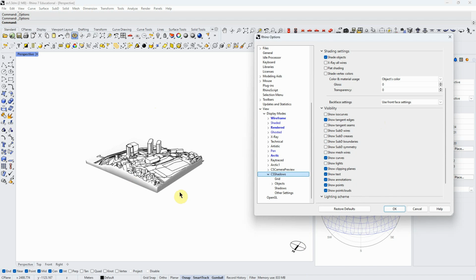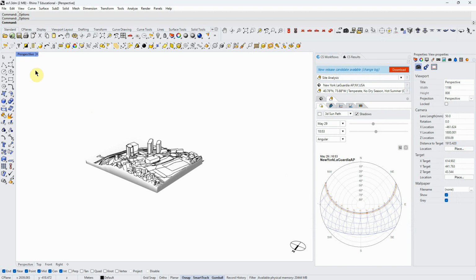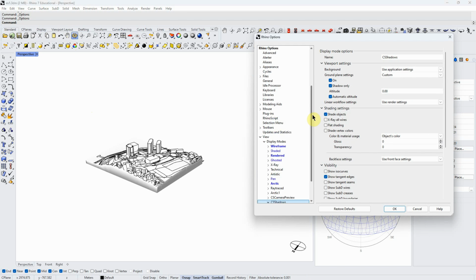It's not working because... by the way, let's go back to that. In Rhino, in the standard tools, there's the settings wheel. You click on that. If you haven't used it before, you've got document-specific properties and Rhino properties. These are the basic setup for your Rhino models that will be consistent throughout. If I close this file and open it again, the settings should be the same.